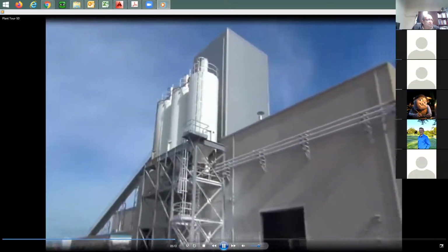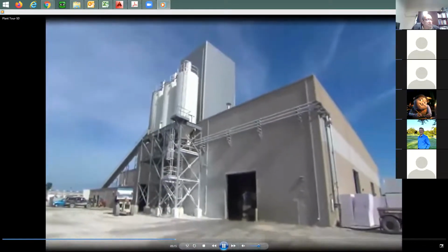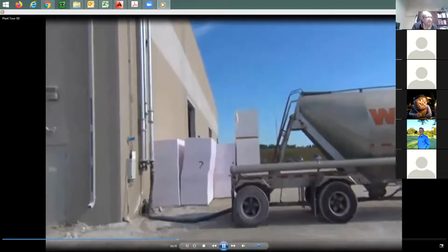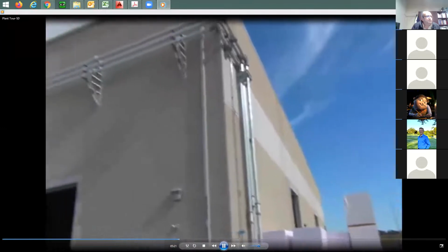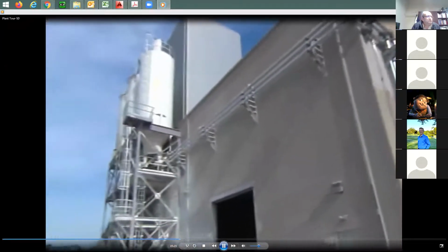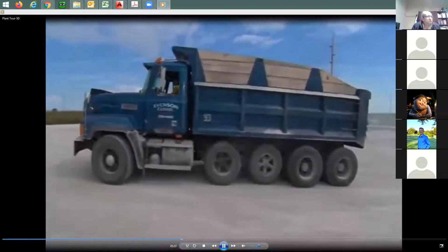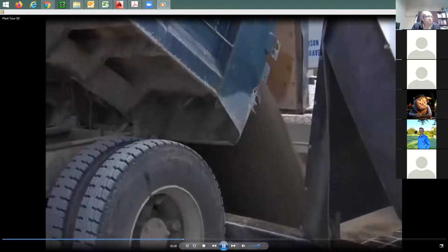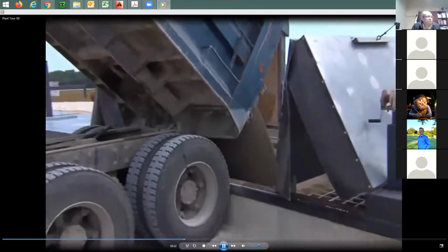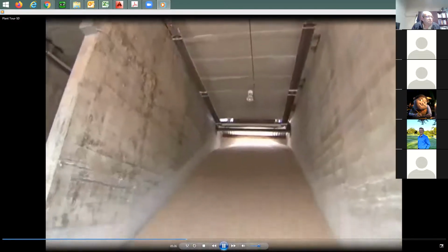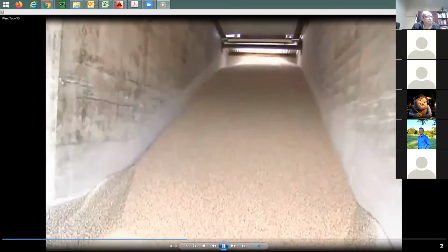Concrete is mixed at the batch plant under tightly controlled conditions. The cement is supplied using tanker trucks. Here, the cement is being blown from the tanker through piping to the cement silos. When needed, aggregates are delivered to bins in the batch plant. The aggregates are stored outside of the batch plant in separate bins. In this case, an enclosed vertical bin system is utilized.